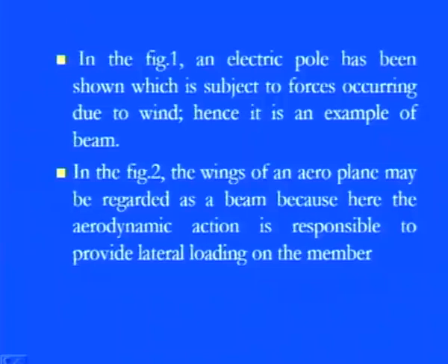Or in figure 2, the wings of the aeroplane may also be regarded as a beam, because the aerodynamic actions, the drag and the lift forces, are exactly perpendicular to the longitudinal axis. The responsibility of this aerodynamic action is just to provide the lateral loading on these particular members of an aerofoil.